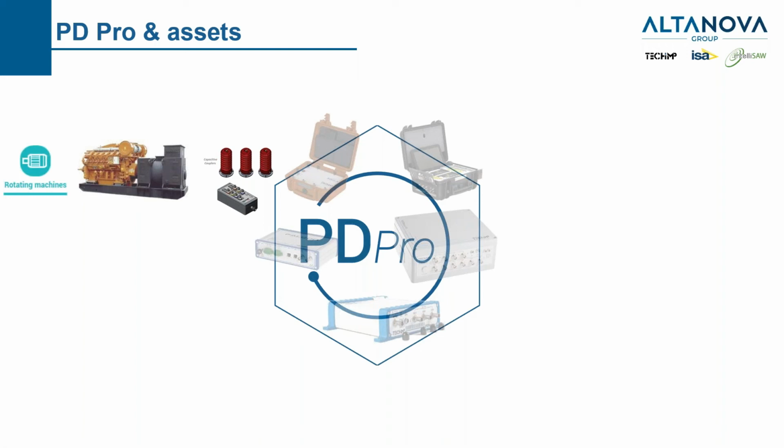Once we have the proper sensor, every asset of the ones I'm going to explain in a few minutes have their own spot in the DB and can be easily managed with the PD Pro. In case of rotating machine, we will select this registry, and we will have to define in the registry which kind of sensor we're going to use. Are we going to use 1 nanofarad capacitive coupler, 80 picofarad capacitive coupler? So together with the PD acquisition, we will also include the information about the test and the asset.